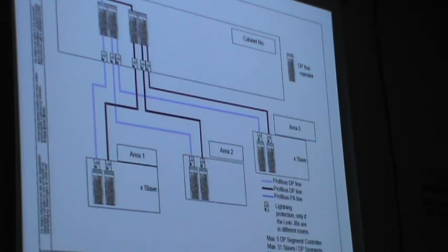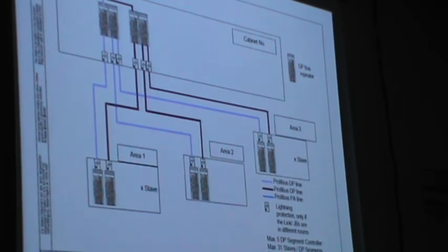And for the motorized valve also, you will get all the details in the DCS. You can open the complete detail about the motorized valve in the DCS. You can check and configure the motorized valve, you can configure the limit switch, and you can configure the actuator position. All the configuration that would be done on the instrument side in the field can be done in the DCS. No need to go to the field, no need to do calibration on the instruments. You can do everything only from the DCS. So that is the use of Profibus.